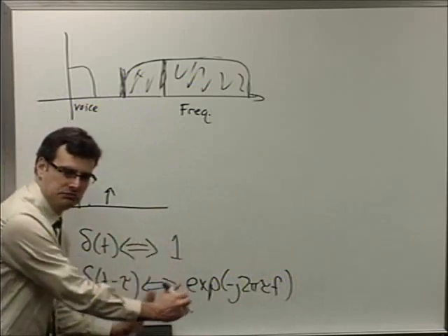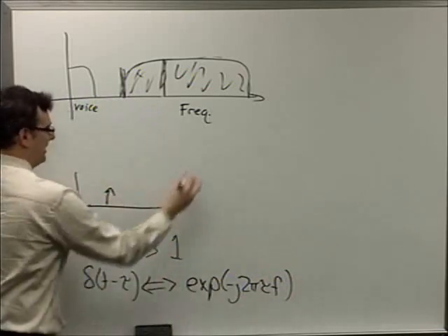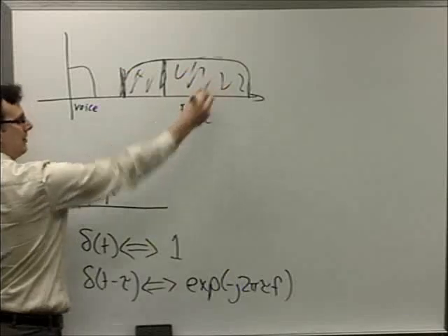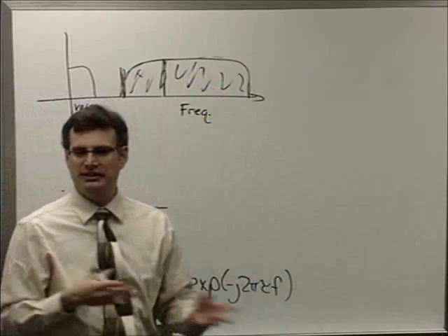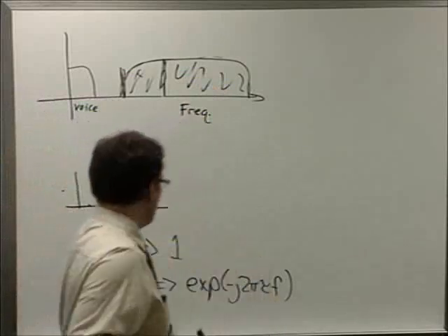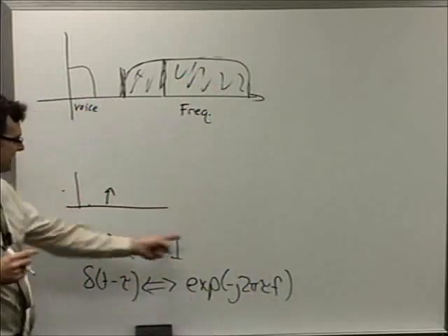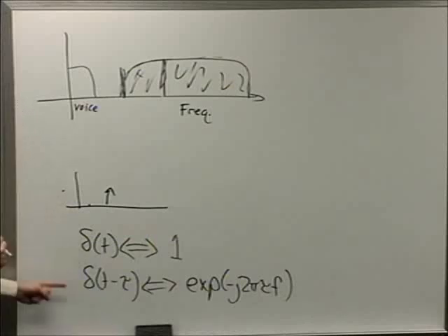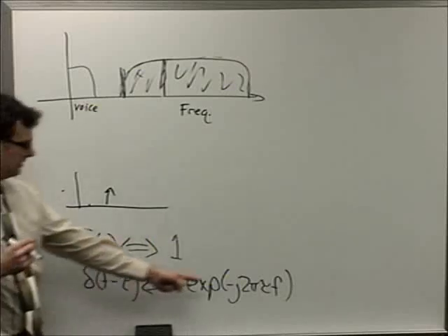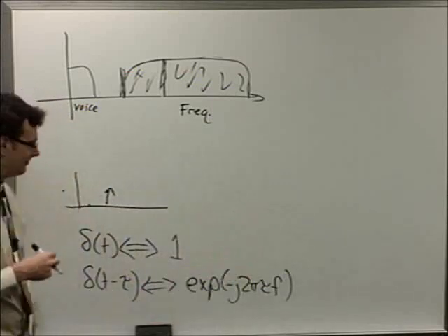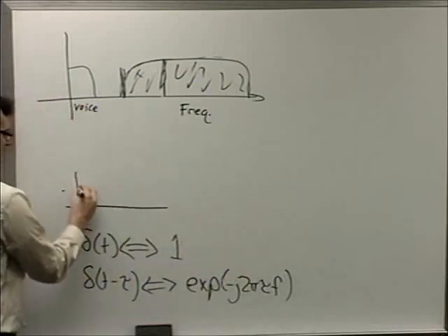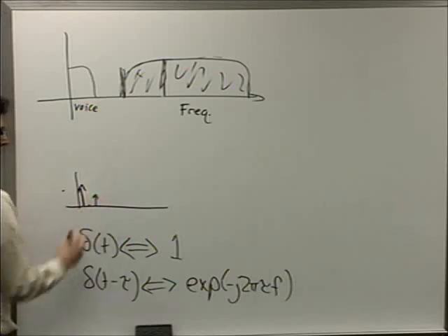Magnitude 1, so it's still constant amplitude in the frequency domain, but there's just this kind of complex phase taper which really just translates into a delay. If you convolve your signal with this, you get the exact same signal out with a delay. No big deal. It's when both of them show up in the same impulse response that you have problems.